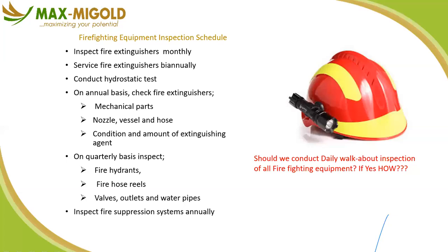And also the sprinkler system, you need to inspect on an annual basis. That should be the inspection and testing point, the ITP, for your sprinkler, so that you can actually discharge the water. I'm sure that there is water on the line without you destroying the sprinkler head. You need to ensure that the rated pressure, 10 bar minimum, should be on the gauges of both the sprinkler and the hydrant. That is the standard.